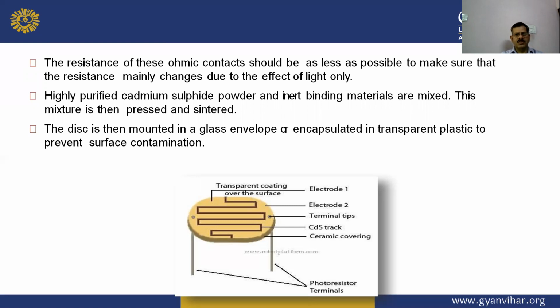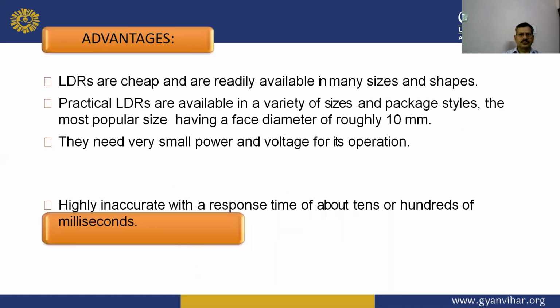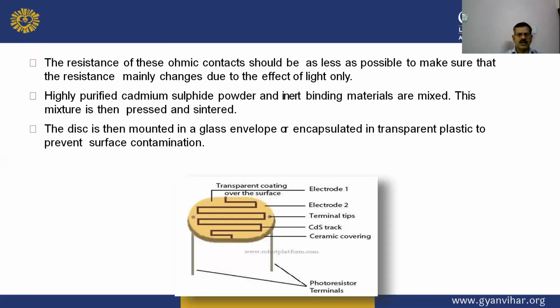Highly purified cadmium sulfide powder and inert binding materials are mixed. This mixture is then pressed and sintered. The disc is then mounted in a glass envelope or encapsulated in transparent plastic to prevent surface contamination. So these are some features about the construction of LDR.